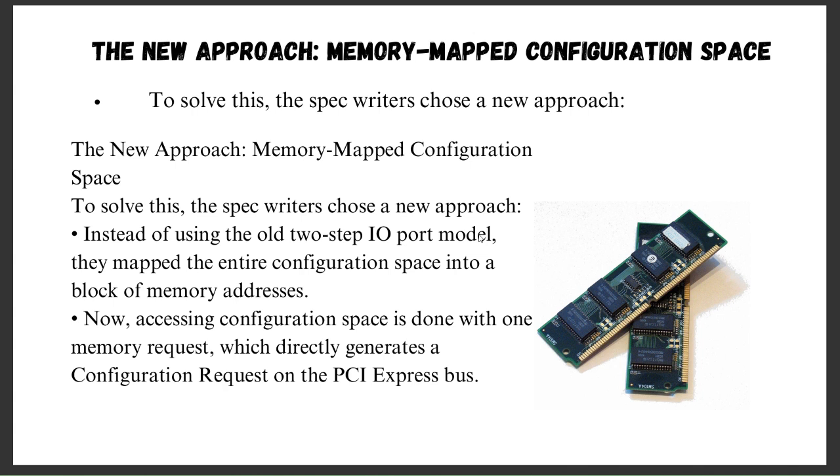However, this is a minor issue because the CPU supports large memory address spaces, that is 36 to 48 bits of physical address space. In such large spaces, 256 MB is insignificant. The issue being addressed is how to access and configure the PCI device efficiently given the limitations of legacy methods, which use a restricted portion of address space for configuration.